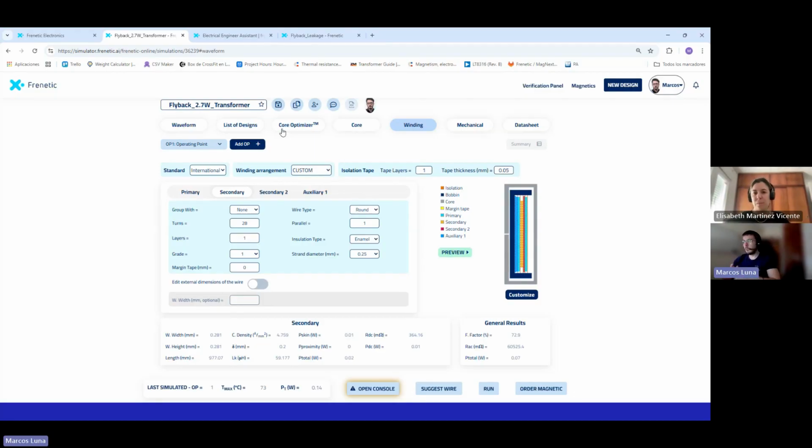Another reason that I also found is that this kind of feedback is more affected by EMI. It's not like the optocoupler, which has more defense against these effects. In the auxiliary winding, you can have some interference from different parts of the system, and this auxiliary winding, if it's close to the secondary side, can induce negative effects on the secondary side that we don't want. So these are the two main reasons for having the auxiliary winding on the primary side.